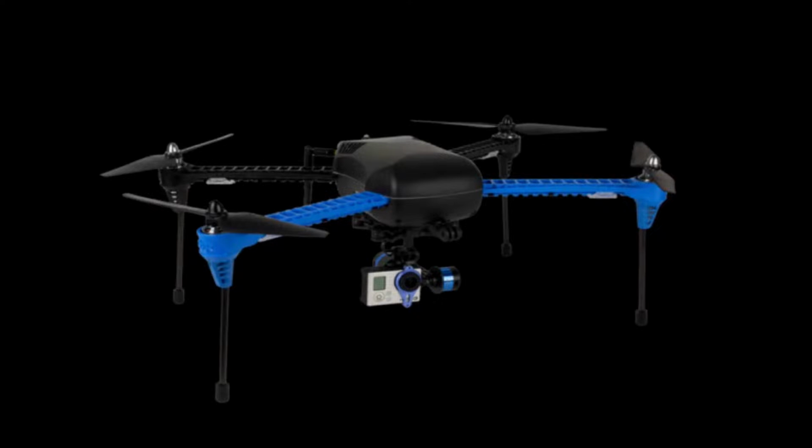One thing this does have is a flight controller, which is called a Pixhawk. A flight controller is essentially the brains that control the motors. They take the sensor data and do the stabilization. The Pixhawk inside this, you can actually take out of that craft and put it in that one, and tell it that it's an airplane now instead of a quadcopter, and it will adapt and be able to fly on autopilot. It takes some machine learning, meaning you have to fly it, and it has to understand how things work, like the aerodynamics. But it's a very versatile flight controller, whereas you can't do that with the DJI products.